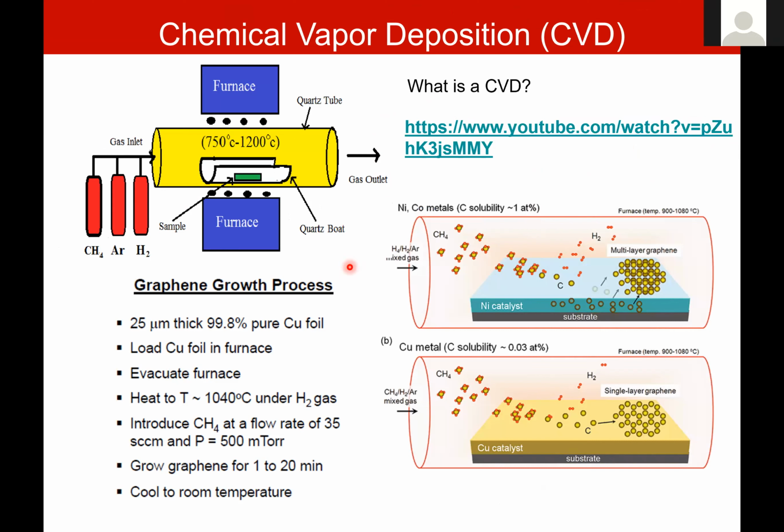So basically, in chemical vapor deposition, you need a gaseous precursor, a substrate, and a furnace. It's basically cooking, right? The difference is that this cooking furnace needs to go to very high temperature. Graphene gets cooked at 900 degrees Celsius. Molybdenum disulfide gets cooked at 800 to 850. So different materials get cooked at different temperatures, and you have to be able to vary those temperatures.